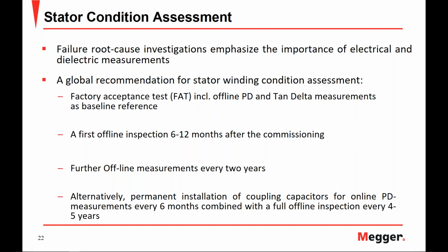Further offline measurements are to be performed every 2 years, or alternatively, coupling capacitors could be permanently installed for online partial discharge measurements every 6 months, combined with a full inspection offline every 4 to 5 years.